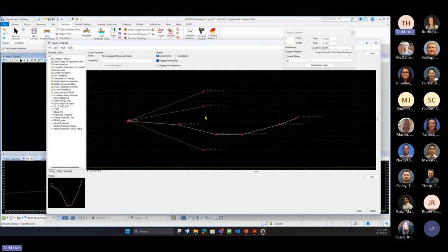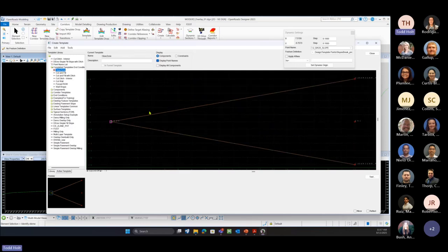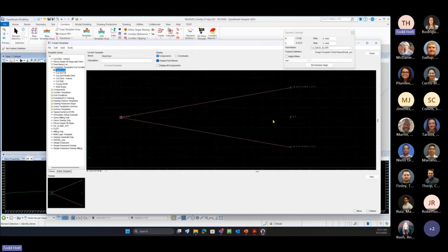So we're going to take a look at the do not construct point property as we draw this. This one gets a little confusing as we work through it. But basically we're going to come in, and if I look at my template endpoints here, we have a clear zone coming from the hinge, and we're going to build a do not construct point out and an end condition. That's going to be 18 feet out that we know, but it's going to have a variable slope. And that's going to draw.